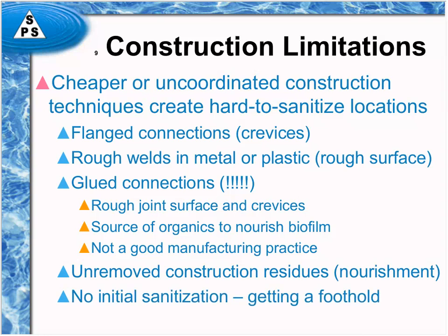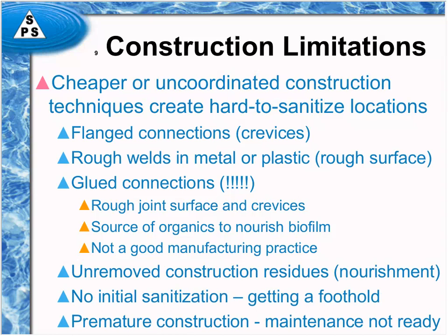Sometimes when a water system is put together, it's not sanitized to begin with. It usually has to be wetted in order to test for leaks and all this kind of stuff. And if there's not immediately following that a sanitization process, then the combination of unremoved construction residues and all the other stuff that's inside a water system will allow biofilm to get a foothold. And once it gets a foothold, it is very, very difficult to remove.